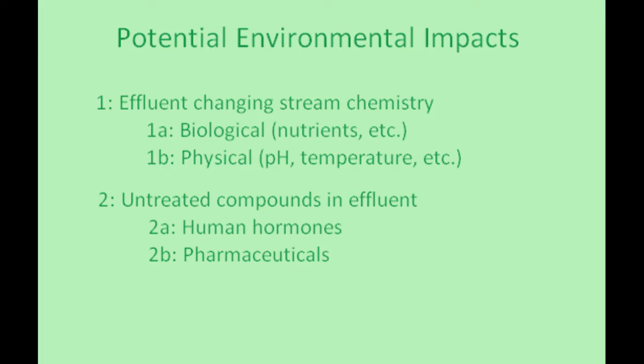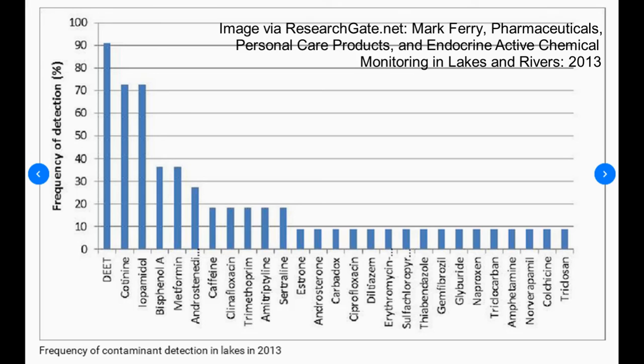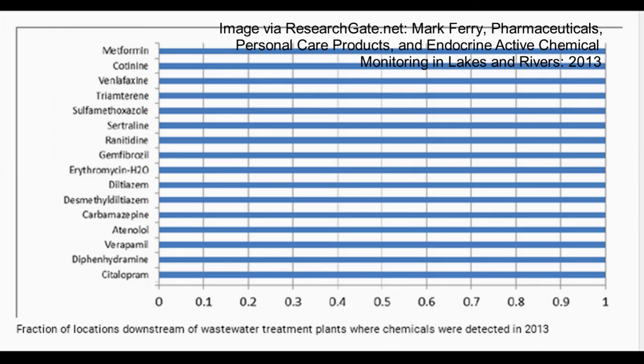Additionally, there are compounds in wastewater that have no available treatment pathway yet. Compounds derived from human hormones and pharmaceuticals are present in effluent, especially for a treatment plant that services a hospital, but neither their treatment options nor their environmental impacts are very well understood. This presents a significant challenge to the future of wastewater treatment. Engineers globally are actively working to introduce cost-effective ways of detecting and treating a variety of currently unaccounted for compounds. In the meantime, they represent a flaw in the wastewater treatment process.